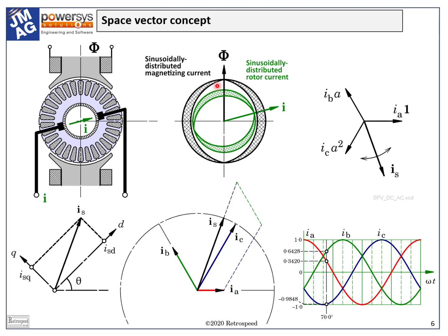In the normal AC machine, the flux phi is rotating at synchronous speed, and the ampere conductor distribution includes all three phases. In comparing this with the field system of the DC machine, there are three obvious differences. First, in the DC machine, the flux phi is stationary, but in the AC machine it rotates at synchronous speed. However, if we imagine ourselves to be an observer on the rotor, the flux will appear to be stationary, and so we can dismiss this difference as a mere detail.